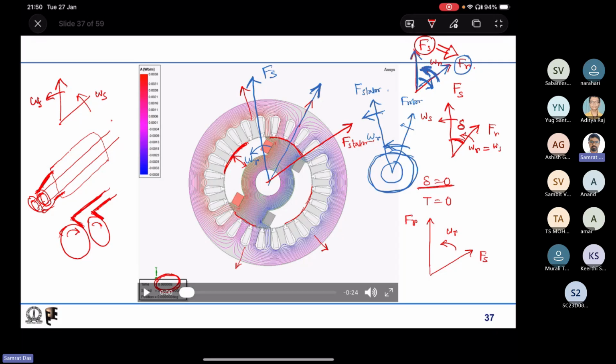If it is rotating as a motor and we want to change it to generation, we can change the excitation in such a way that, knowing where the rotor magnetic field is, the stator magnetic field lags. Then it can instantly shift from motoring to generation and generation to motoring.